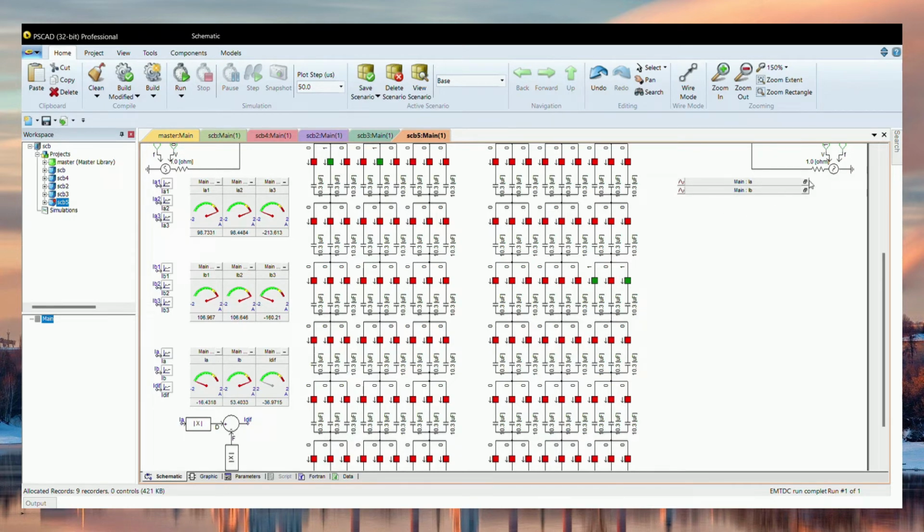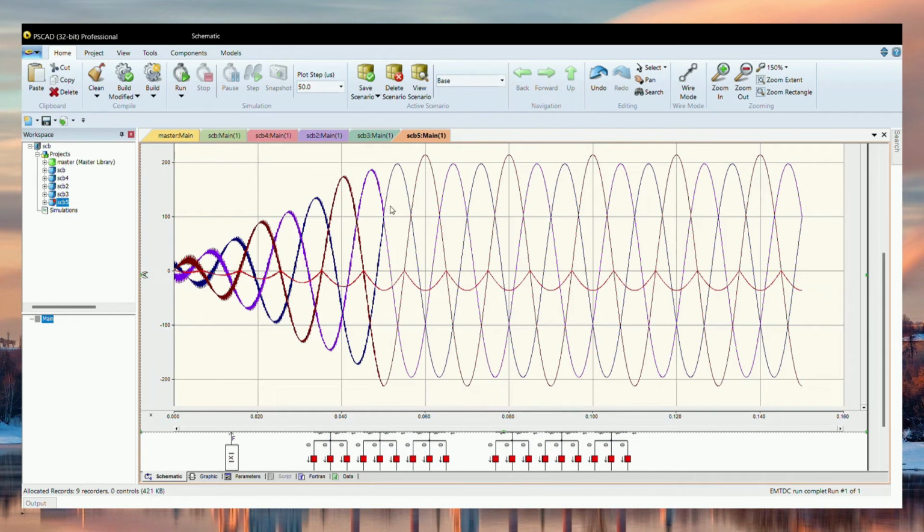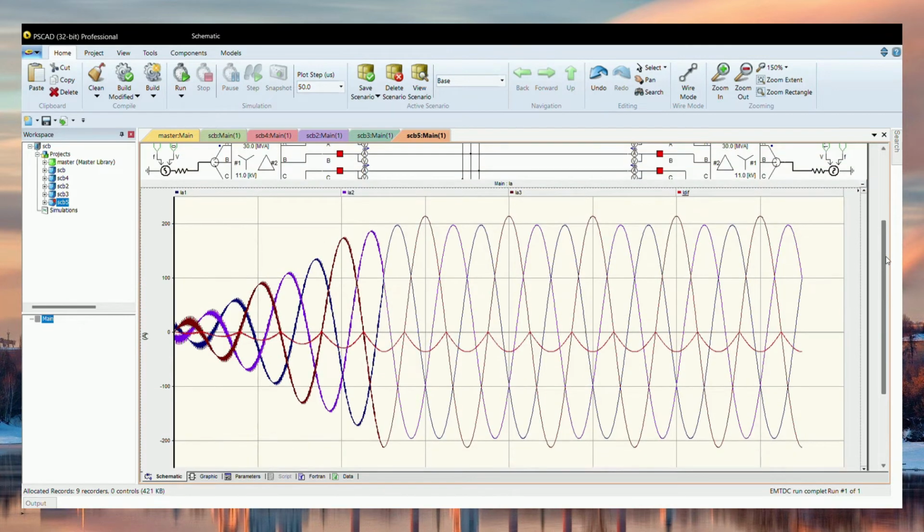And now, based on the graph IA, based on IA1 the blue line and IA2 the purple line, we can see that the I peak is lesser than the IA3, the normal no fault capacitor bank. So we can see that this happens because a faulty capacitor will decrease the current value. The current peak for IA1, IA2 is lesser than IA3.